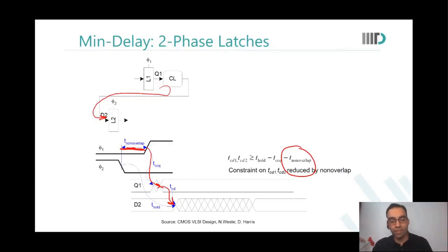Is this thing clear for the two-phase latches? Why is phi1 after the phi2? This window shouldn't be before, because it will come after also, no? I consider the hold time requirement of L2. Because L2 sampling edge closed, now I want input of L2 to be stable. What will spoil the input of L2? The rising edge of phi1. So the rising edge of phi1 that comes after falling edge of phi2 is what I'm interested in, is it not?